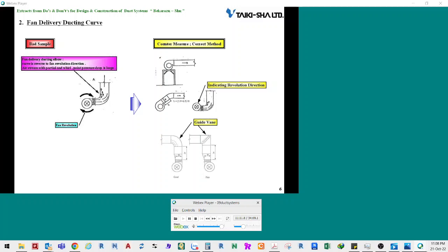It is best if the duct behind the fan outlet is straight. To make it straight, you should adopt pedestals with longer legs or those hung from the ceiling. It is, however, difficult to do so. In that case, if the duct should be turned, turn it in the direction of the revolution of the fan blades.